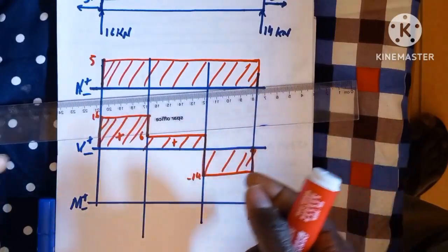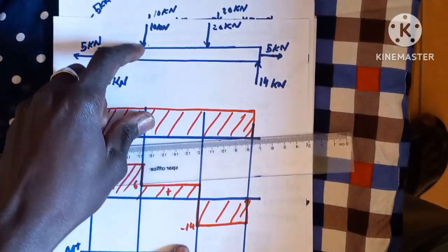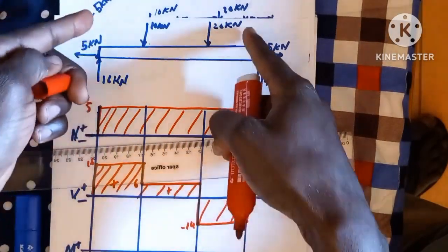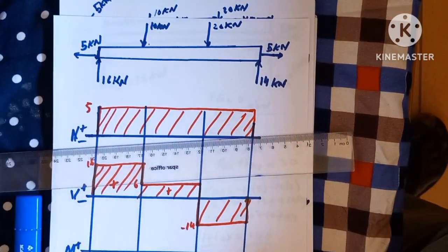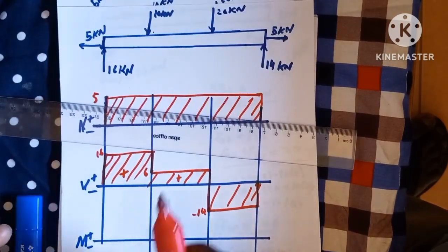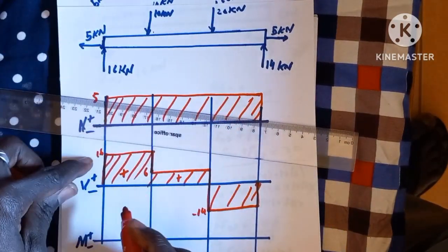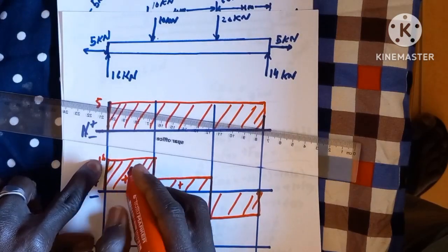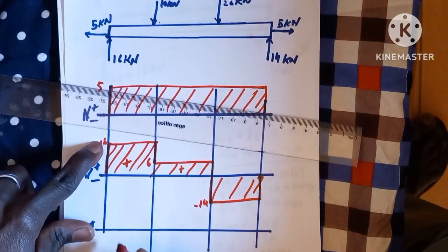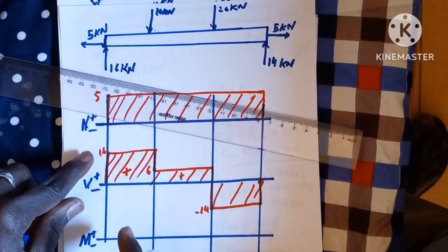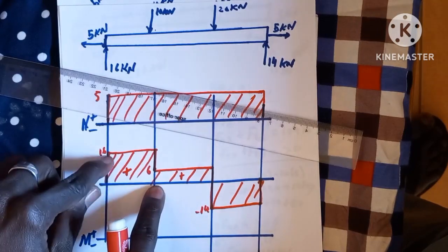So in this case, we have forces that are pushing down on this beam, trying to break the beam, and we have a support that is trying to resist that, right? So considering this one, we have 16 here, right? The area under the curve of this shear force is going to be the bending moment. For a rectangle, area is the base times the height, right?